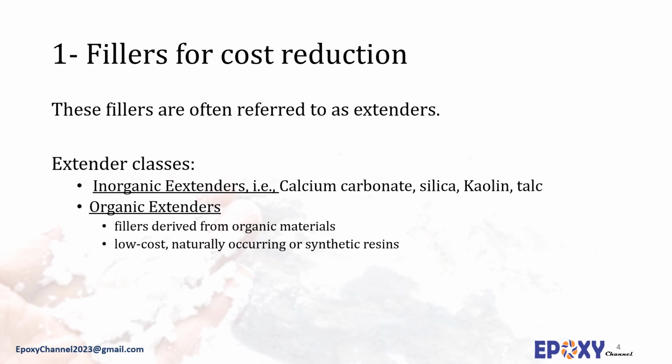Kaolin clay is another naturally occurring mineral that is often used as an extender in adhesive formulations. It is hydrated aluminum silicate with a hexagonal plate-like crystal structure. In addition to reducing cost, kaolin clay provides shrinkage control, dimensional stability, viscosity increase, and also pigmentation. Talc is a hydrated magnesium silicate which is used for lowering the cost of the formulation with a minimal effect on physical properties. Because of its plate structure and aspect ratio, these extenders are also considered reinforcements.